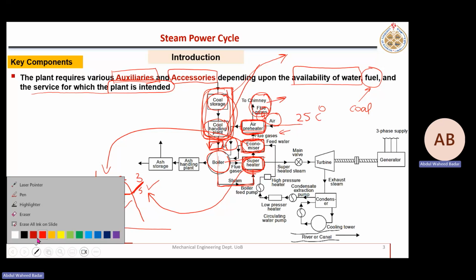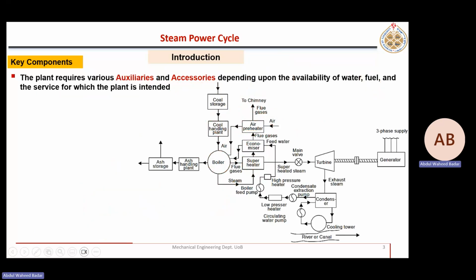Okay, so things are very messy. So this is the part we just covered. Now, finally, it goes into the chimney. The part which we can add here separately is the furnace. Let's show the furnace separately where the combustion is taking place. Then here this sequence can be changed a bit because these highest temperature gases first go to the superheater, then to the boiler, then to the economizer, then to the air preheater.